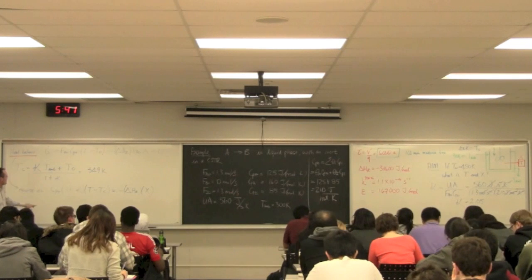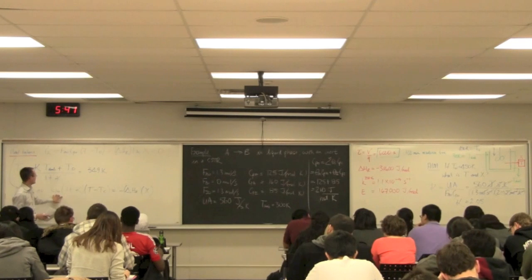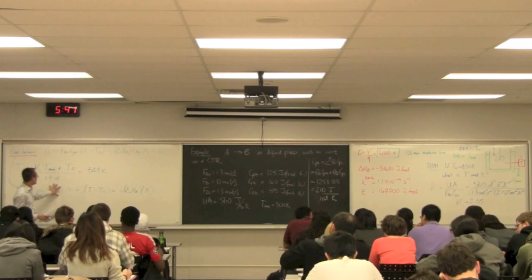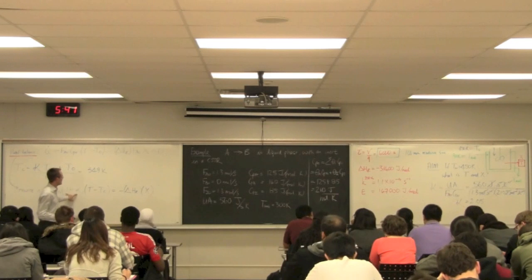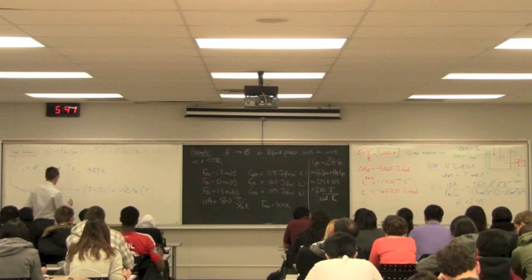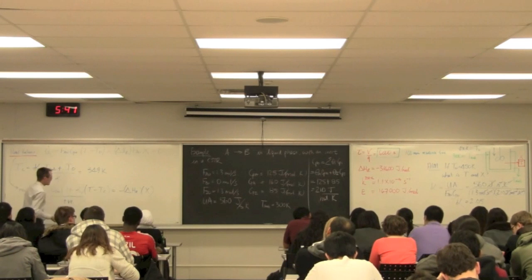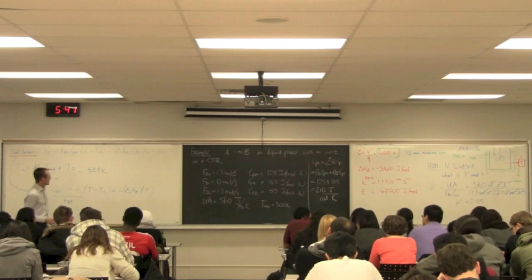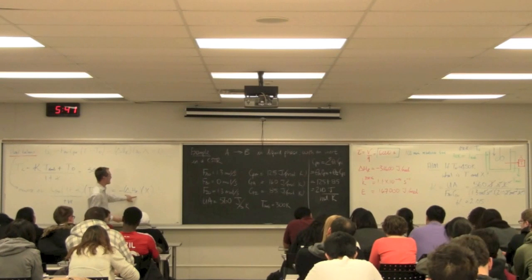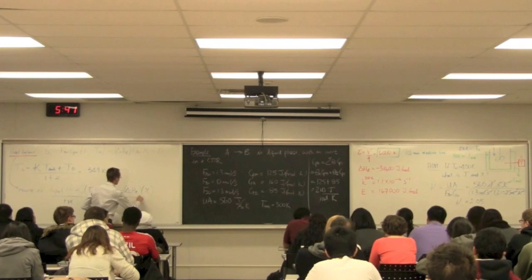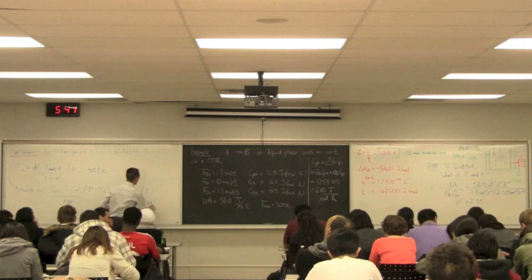But we also established last night that we can actually get a slightly better estimate for T from this equation over here. C_P0 is a positive quantity, kappa is a positive quantity, so this all here is positive. Heat of reaction, delta H_R, is a negative quantity, but a negative times a negative gets me a positive over here. Conversion must always be positive.